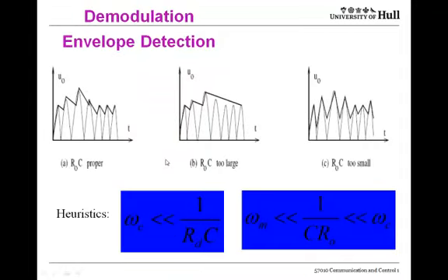So these graphs illustrate how the output of an envelope detector tracks that of a signal. For all of them, in the leading edge where the modulated signal is increasing, the output of the envelope detector tracks it. But when the input drops again, the envelope detector switches to the other mode and slowly discharges. So although these look like straight lines, they're the beginnings of an exponential decline.